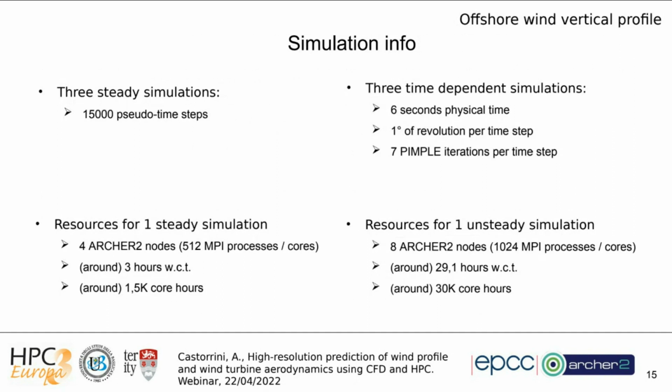So, some information about the simulations on ARCHER2. The 3 steady simulations with axial wind run for 15,000 pseudo-time steps to arrive at convergence. Pseudo-time steps because, for steady simulation, the SIMPLE algorithm implemented in OpenFOAM makes a sort of time integration, but with a pseudo-time to arrive at convergence of a steady state solution.